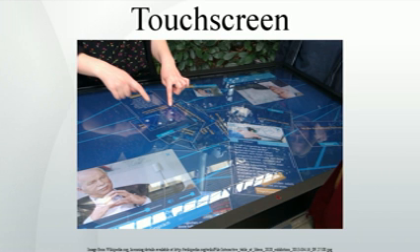Bringing a finger or conductive stylus close to the surface of the sensor changes the local electrostatic field, which reduces the mutual capacitance. The capacitance change at every individual point on the grid can be measured to accurately determine the touch location by measuring the voltage in the other axis. Mutual capacitance allows multi-touch operation where multiple fingers, palms or styli can be accurately tracked at the same time.